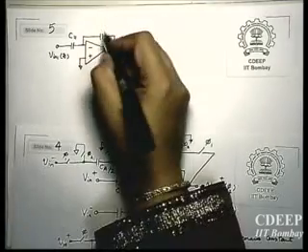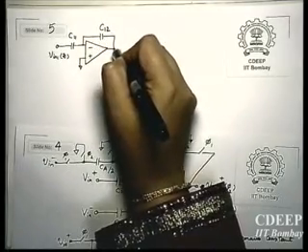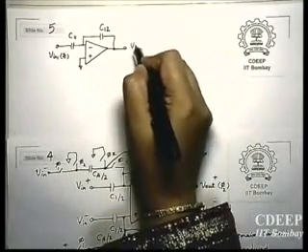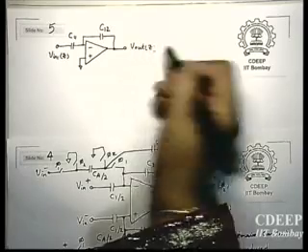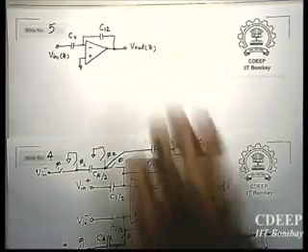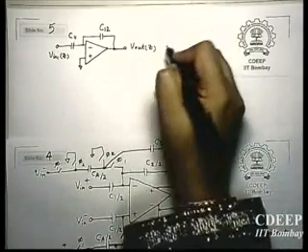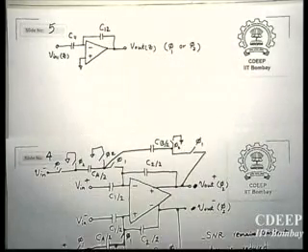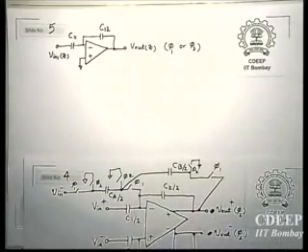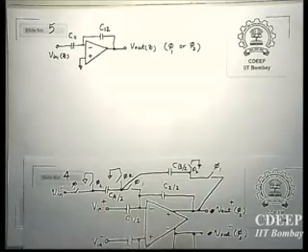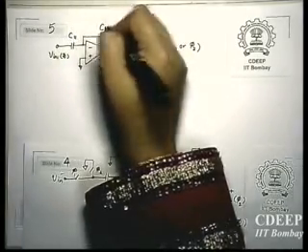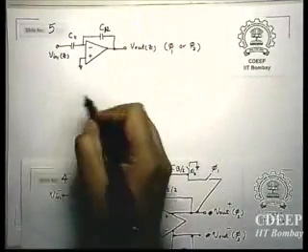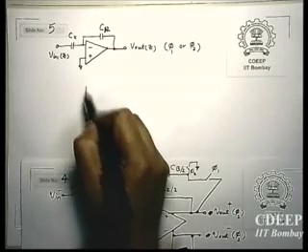Now we have just different standard architectures. This is just a simple gain stage. So therefore this is your Vout Z. Here you don't have to worry about sampling. You can sample this Vout either in phi 1 or phi 2, right? It depends on the other parts of the circuit. So this is just the gain. I call it C2. The reason is I want to use the same integrator with different inputs, and then the other part can again be the same.